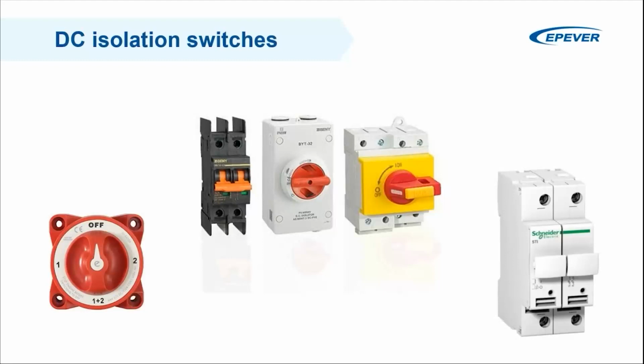Normally we isolate the positive battery cable, as I mentioned, but this really depends on your local standards and regulations. And these also have a voltage and current rating. It's important that you check on the product labeling how much current and how much voltage this can tolerate, and should be in range of your requirements.